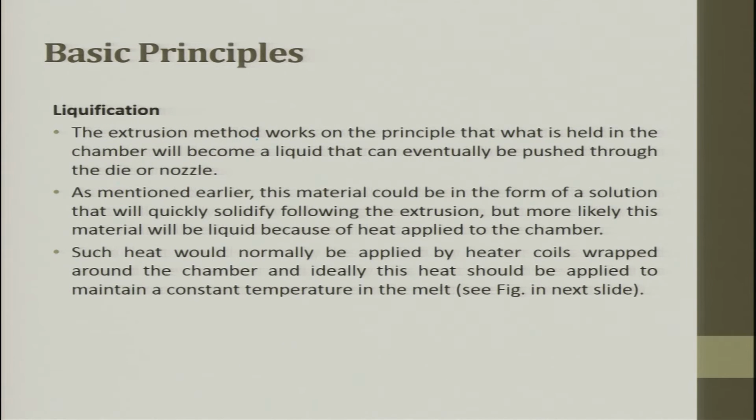Liquefaction. The extrusion method works on the principle that what is held in the chamber will become a liquid that can eventually be pushed through a die or a nozzle. As mentioned earlier, this material could be in the form of a solution that will quickly solidify following the extrusion, but more likely this material will be a liquid because of heat applied to the chamber.